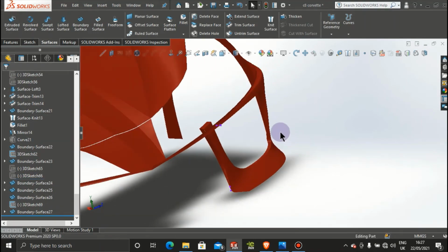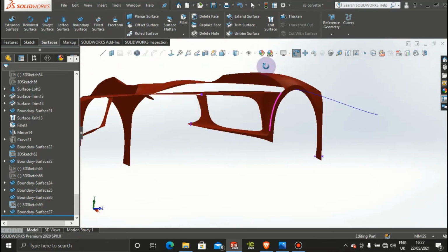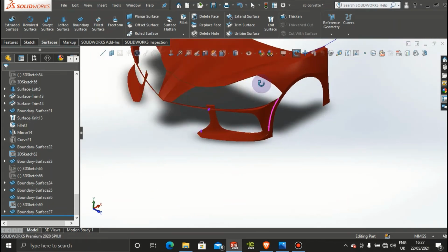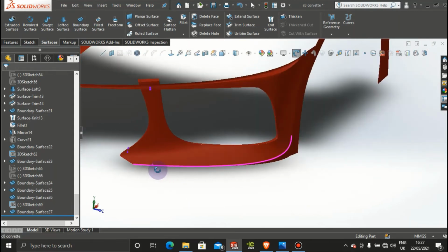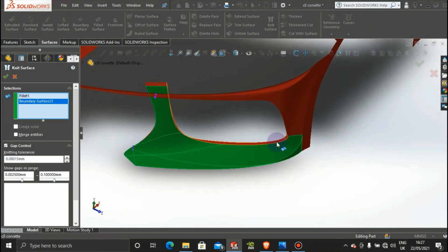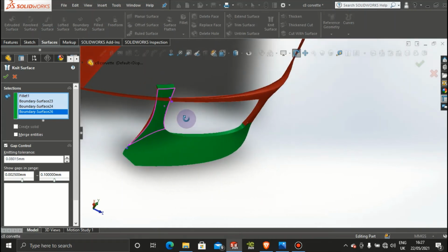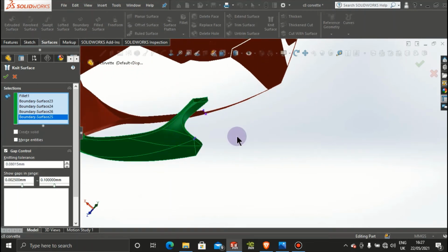Let's hide that line. And we are almost tangent there, but that's not very visible in the corner. All right, so this is one surface, but we can put it into one surface and mirror these over to the other end. But we are nicely closed on this side as well. Okay, so let's knit some areas here, but don't knit anything to the body, obviously, just this area here. So let's knit that. This one, this one, this top part, this one, and we still need to close this small section off.